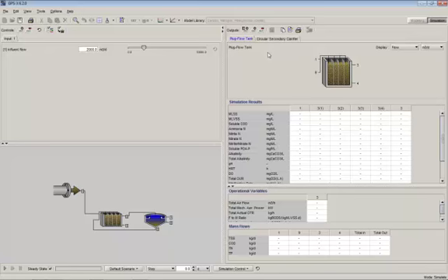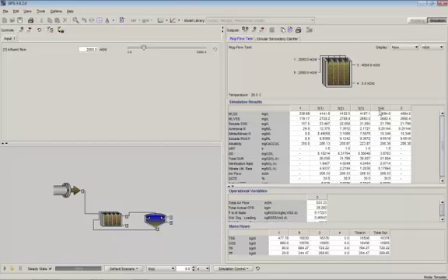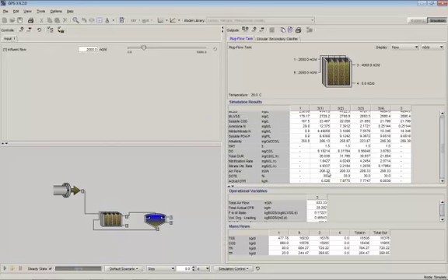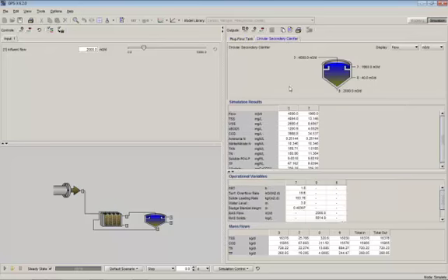And so if I run a simulation right now, you go to the lower left-hand corner and hit Start. This little table specifies all of the details that are for this particular unit process: mixed liquor, and nitrogen and phosphorus and BOD and COD and so on. Some other details about the aeration and a little mass balance at the bottom there. And if you go to the clarifier page, you get stuff that's specific to the clarifier, like sludge blanket height and so on.